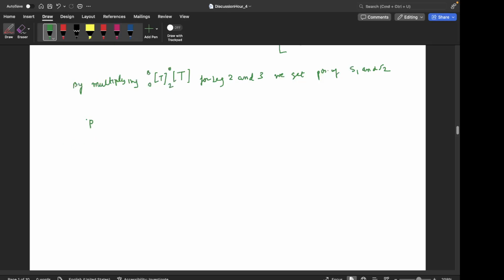So position of S0 in base frame B, that is B minus L1 C1, 0, L1 S1, then B, then this is S1, and this is minus B by 2 plus L2 by 2. So this is the column of the transformation matrix that you finally get, the last column. So that last step, I have done the entire thing. This last step you can do the calculation for the other two legs and just verify with this result.